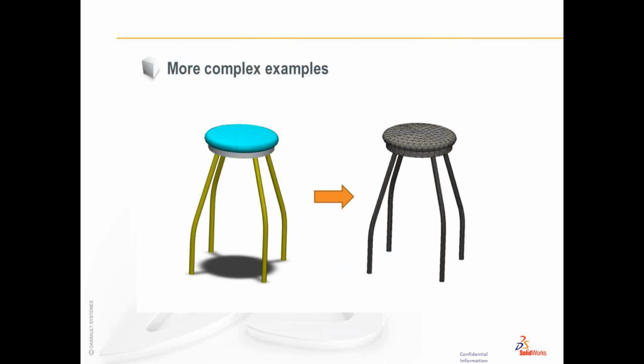So these are equations that you might find in a textbook that you can apply, doing hand calculations to typical shapes, predictable geometry. But in reality, the world's not like that. We have structures that are much more complex than a column and loading usually. This stool is an example out of the Simulation Professional course, where we talk about linear buckling. So this type of geometry would be a little bit more difficult to apply hand calculations to. And on top of that, we have the different end conditions for the feet, and they may greatly affect how or when buckling may occur.